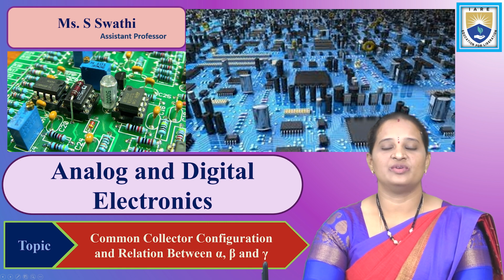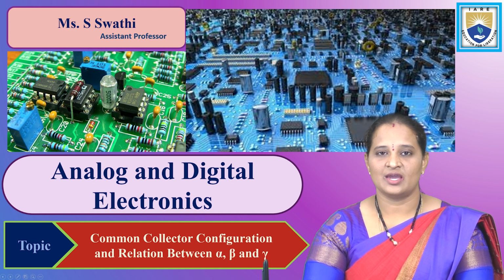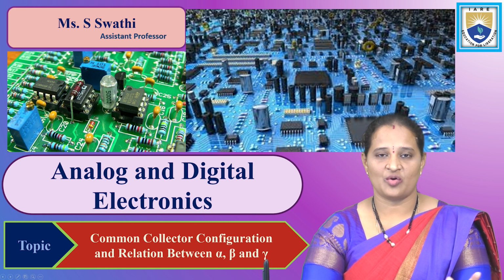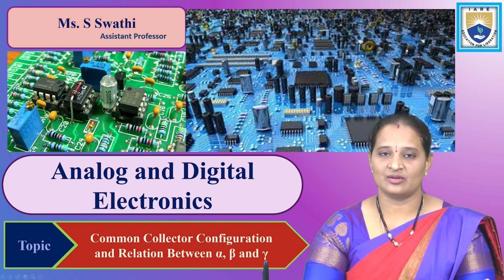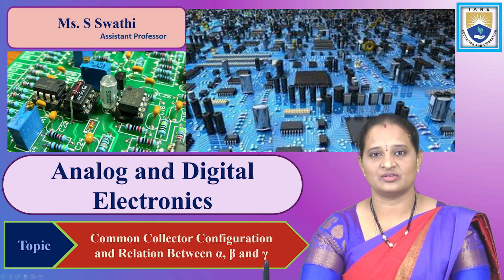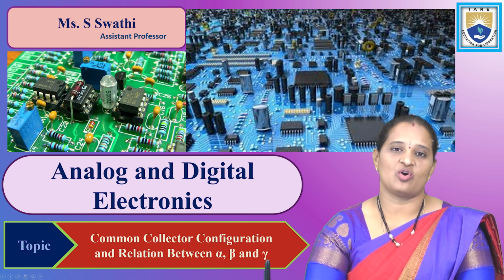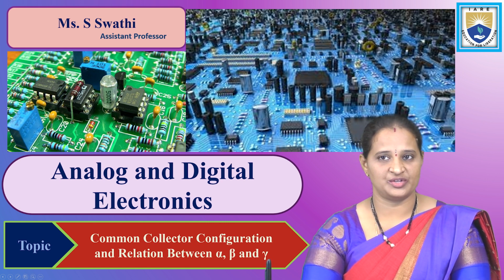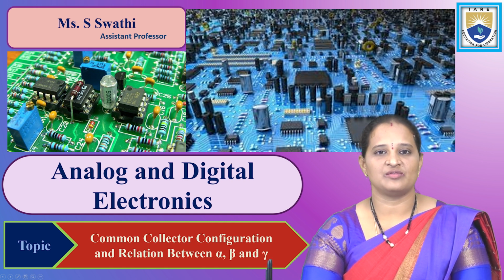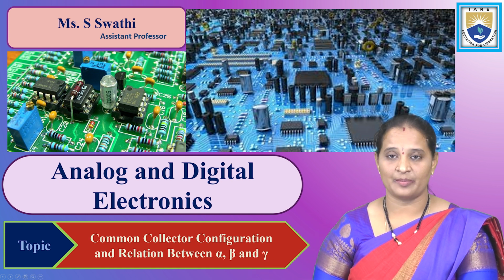In this lecture, we'll discuss the common collector configuration of the transistor, its VI characteristics, that is the input and output characteristics of the common collector configuration. And also we'll discuss the relation between the current amplification factors of the three different configurations of the transistor, that is common base, common emitter, common collector configuration. Those are alpha, beta and gamma, and the relation between these current amplification factors, that is alpha, beta and gamma.